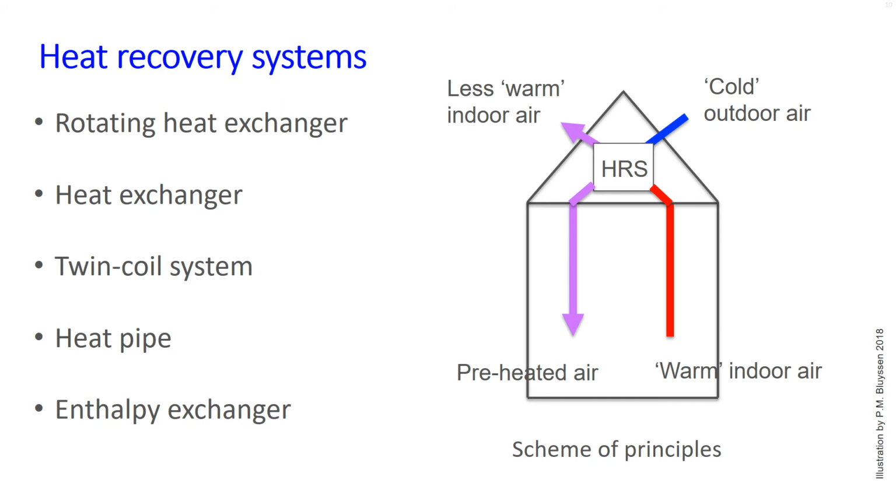In a rotating heat exchanger, the warm return air heats the wheel, and by turning the wheel, it reaches the air supply side, where the supply air is heated and sometimes also humidified. In this way, rotating heat exchangers may transport pollutants from the supply to the return side when in use.